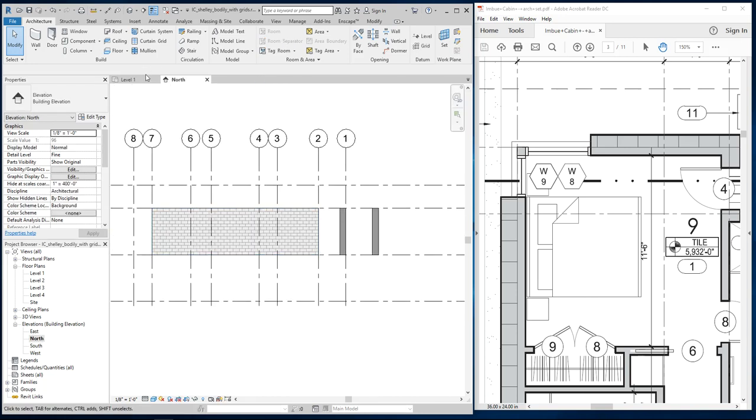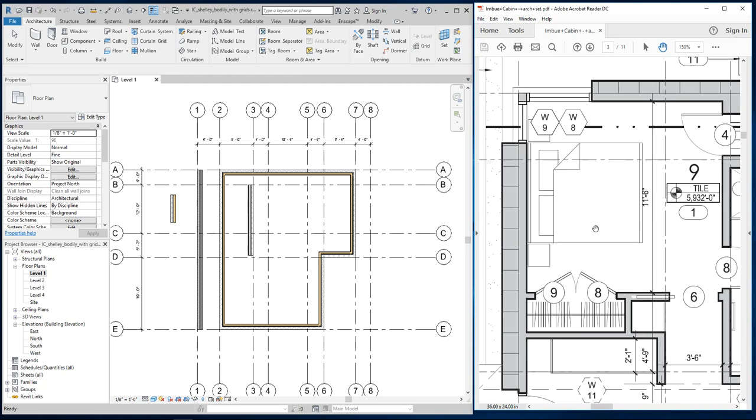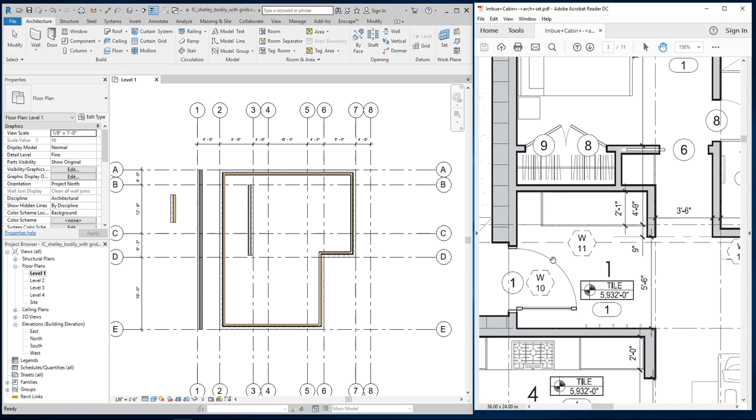All right. Any questions about creating wall types or editing wall types or not yet? Good. Okay. Well, let's talk about doors then. Doors are easy. Doors and windows are actually really easy in Revit. So I'm going to go to level 1 here, and I'm going to close all my hidden views there. The next part of your assignment will be to start adding doors to this project.